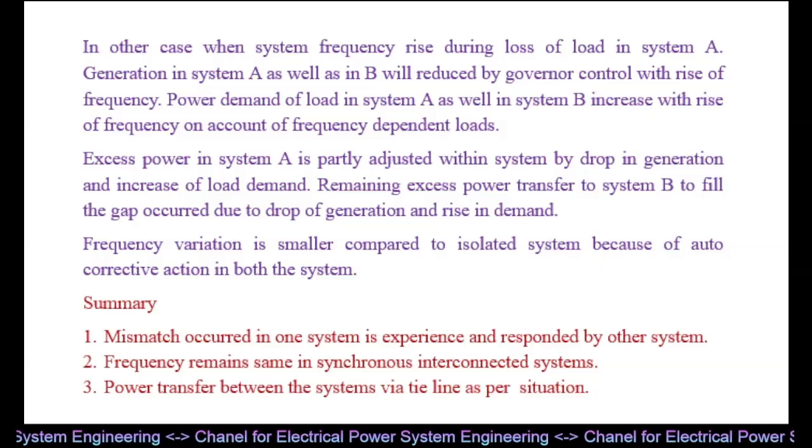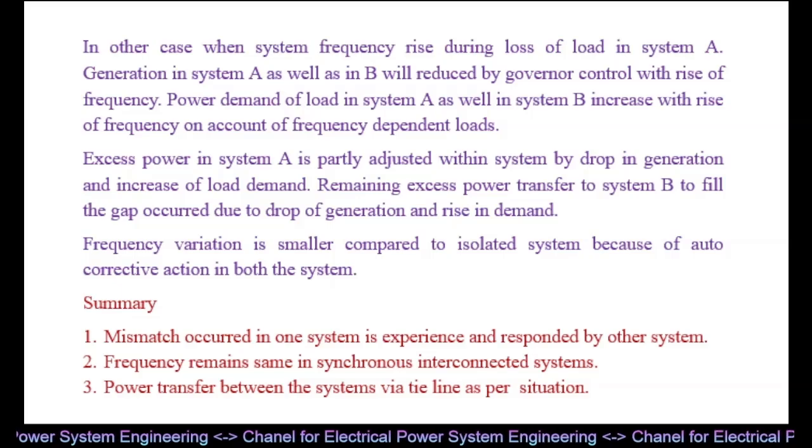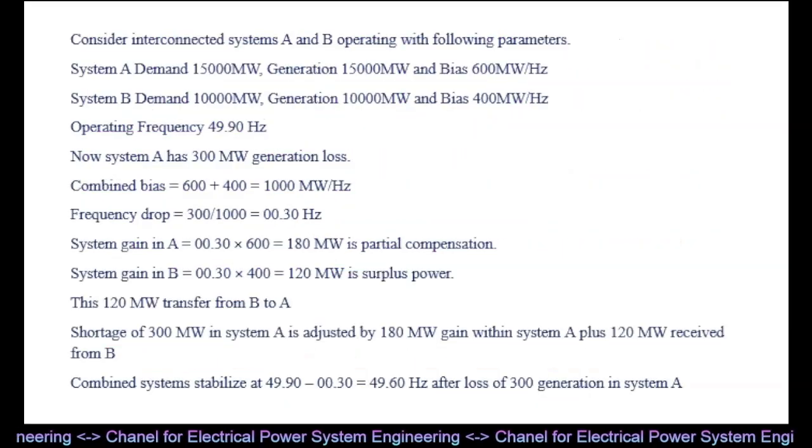Summary: 1. Mismatch occurring in one system is experienced and responded to by the other system. 2. Frequency remains the same in synchronously interconnected systems. 3. Power transfer between the systems via the tie line as per situation.